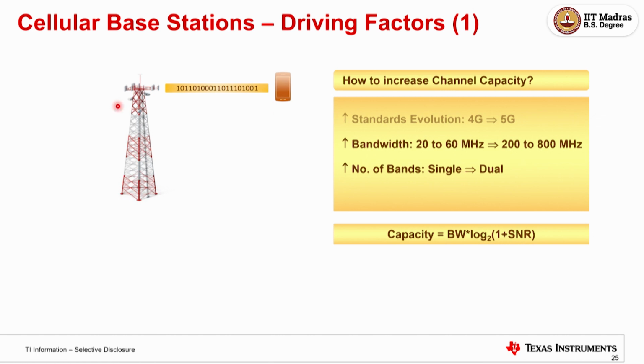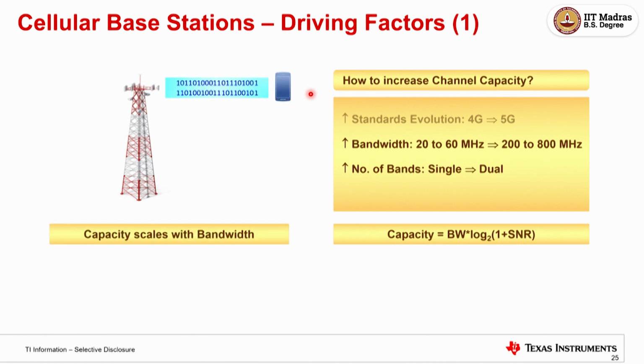The other thing, I'll explain what this is. This is like saying the cell tower is sending this information to your mobile. There's something called multi-band. Like I said, Airtel gets one band in one frequency. You can send only that much information. You can pack whatever you want, you do modulation, you pack that. But suppose I want to double the information. Airtel would also have got a band at a different frequency. Let's say they got a 700 megahertz spectrum.